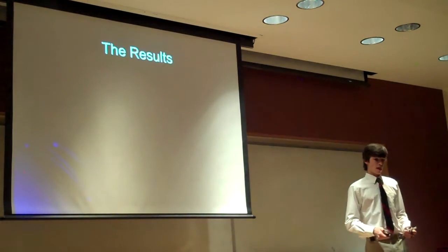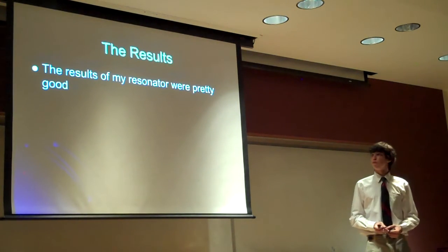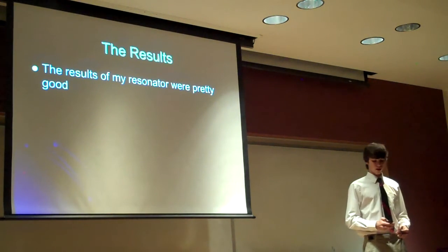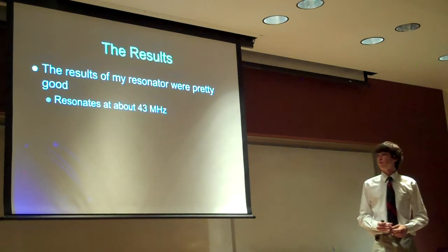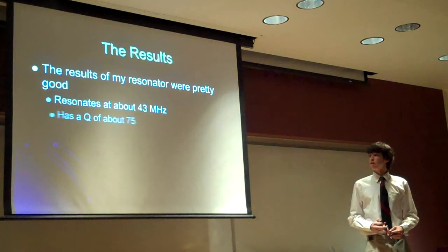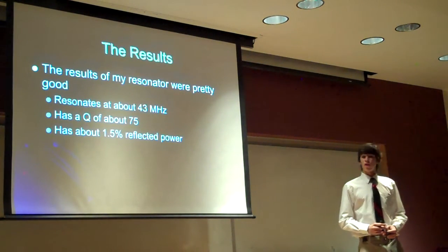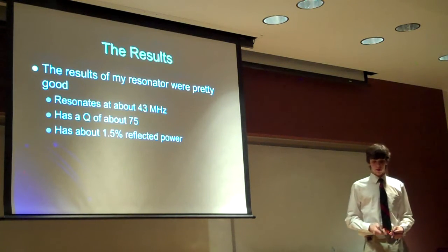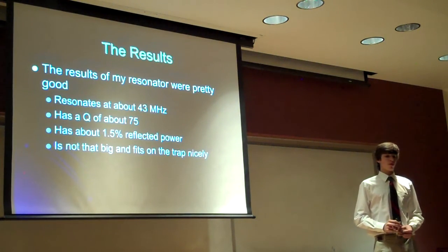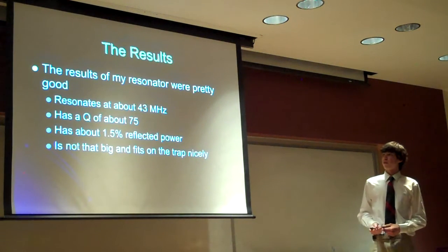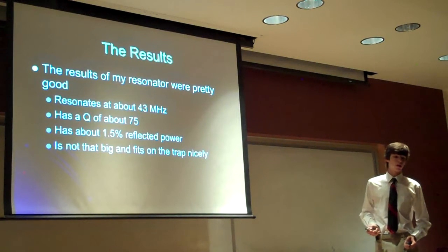So the results. The results of my resonator were pretty good considering I only had 4 weeks and I came in here without ever building a resonator before. So my resonator resonates at around 43 megahertz, and it had a Q of about 75. And then it also had about 1.5 reflected power, and it was fairly small, so it fit on the trap pretty nicely.